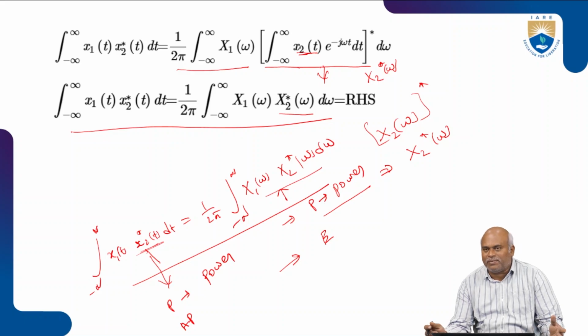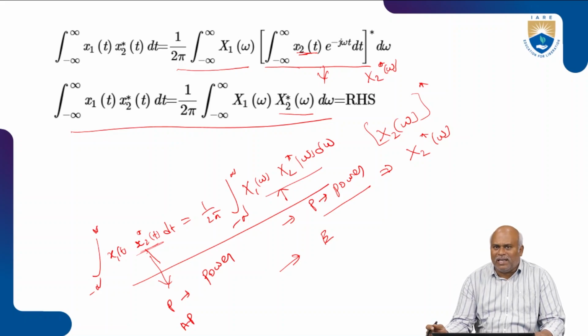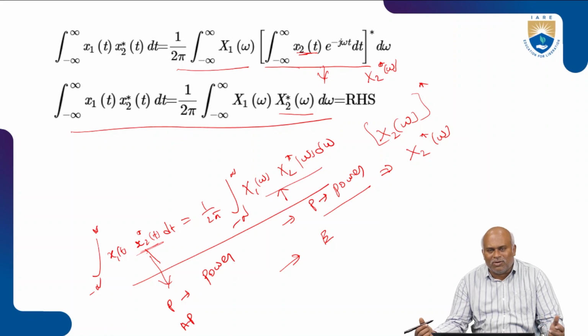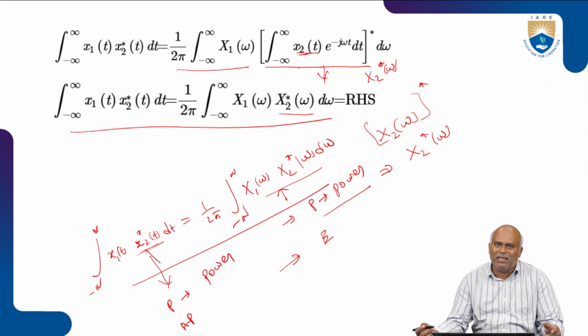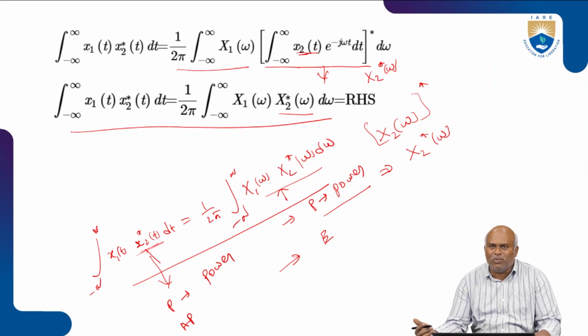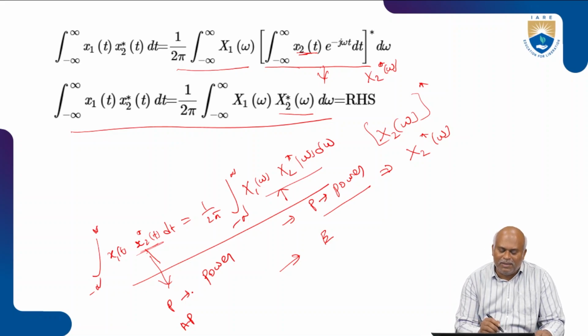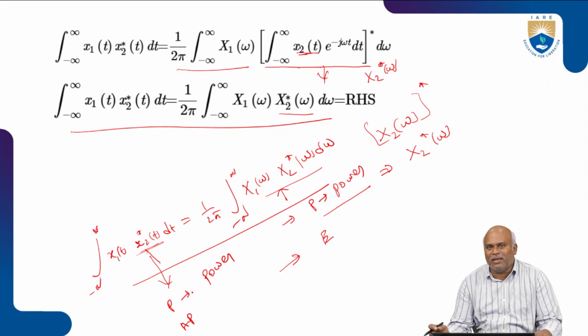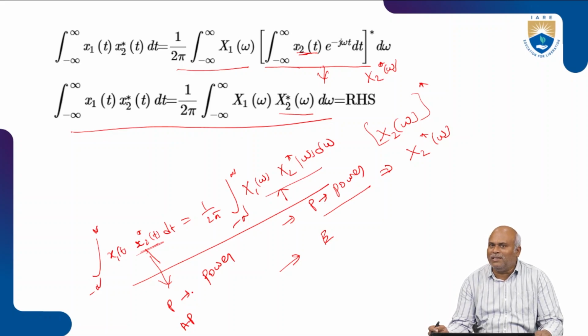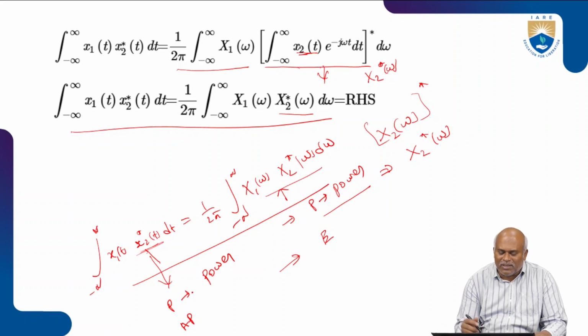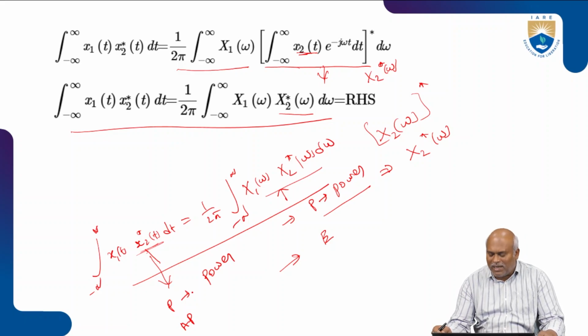So that means, as per the Parseval relation, if we take x1 and x2 as complex-valued signals and the signal is periodic, it satisfies power. The produced output will also be represented as power, even though it is in the frequency domain, while the input is in the time domain. If the signal is represented as an aperiodic signal in the time domain, the output of the Fourier transform is represented as energy in the frequency domain. Okay, this is called the Parseval relation.